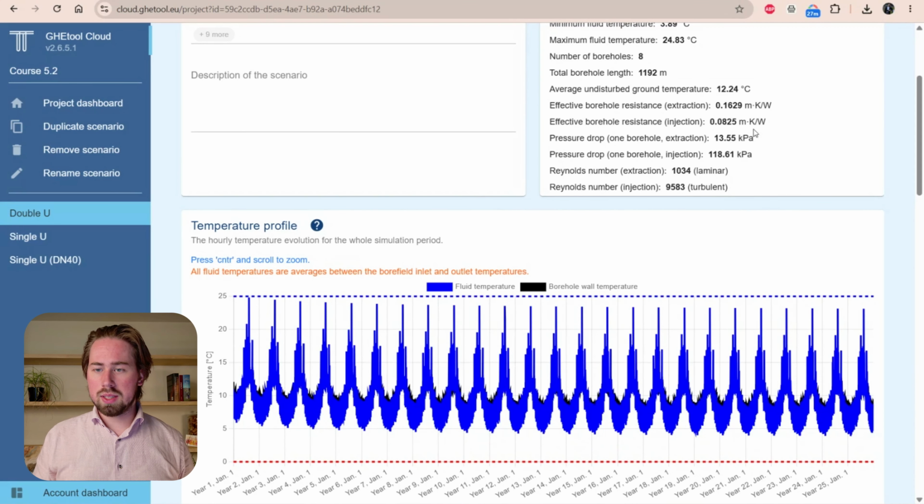So our borehole resistance and injection was as good as it can get. A turbulent W is very, very good. Now we go to an insanely turbulent single U, which is even better, but the problem is that now we have only 1 U-tube to exchange heat instead of 2, making this in the end a worse effective borehole thermal resistance, as well as we cross the limits in this case.